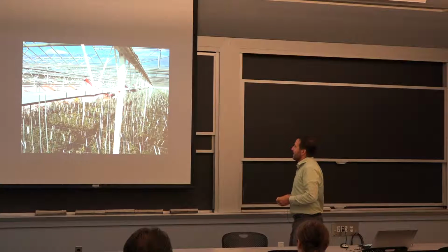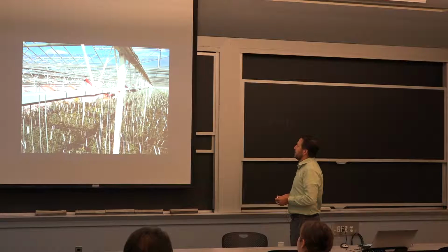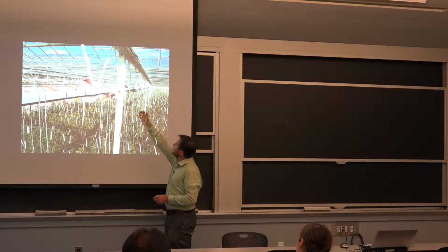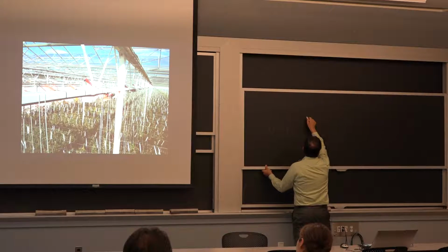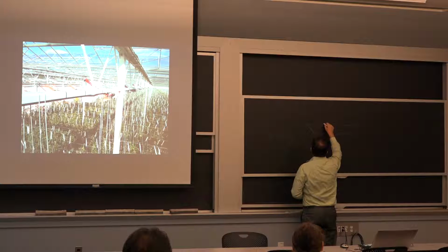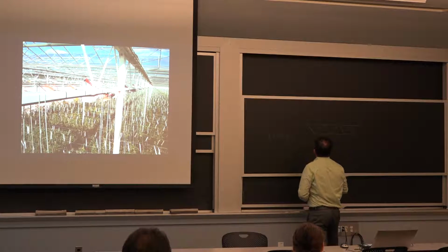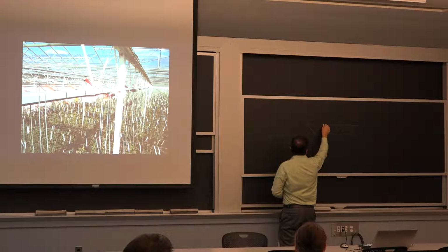But the main issue and the reason why it actually broke are these joists that are essentially the main structure connecting. So the joist connects these columns to the entire roof structure. So a typical joist has an upper chord, a lower chord, and you see those anywhere you go into a Walmart or at the airport or a warehouse. So upper chord, lower chord, and the diagonals is the image I was showing you on Monday.